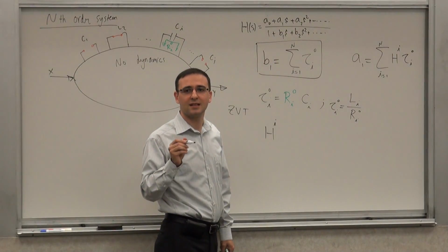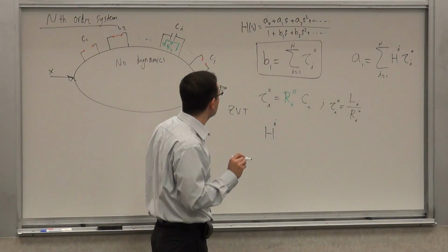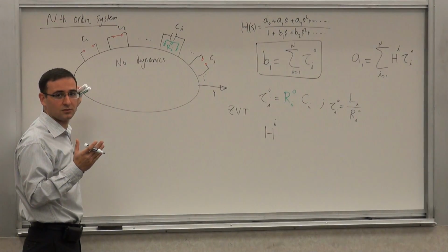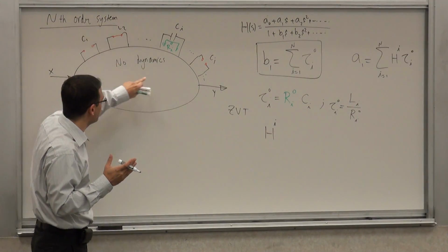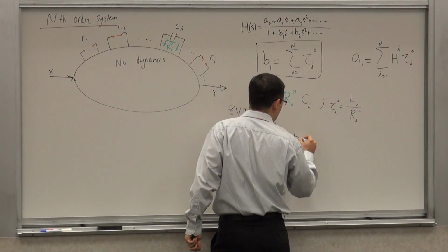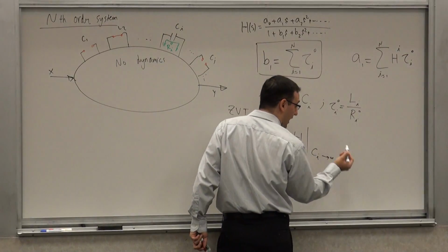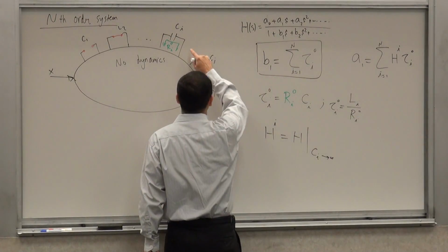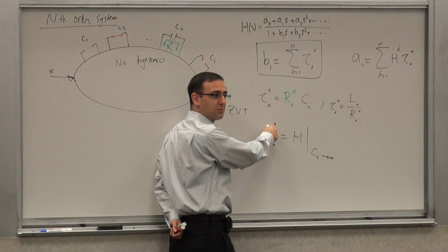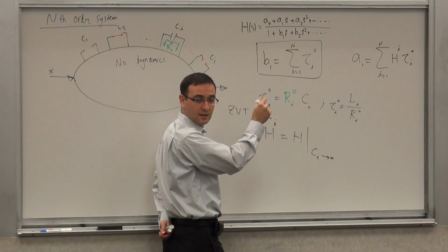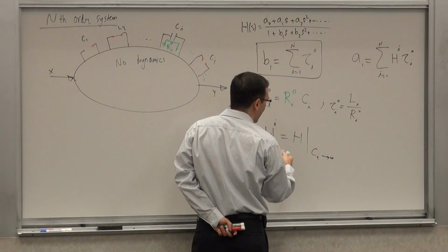It's the ith order transfer constant, which is the gain. It's the low frequency transfer function, called the transfer constant, from the input to the output. So it's H when Ci is infinity, or Li is infinity, that particular element, because you can see that's what our notation means, right? Anything in the superscript is the index of what's being infinite value.